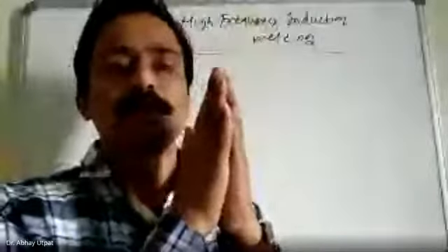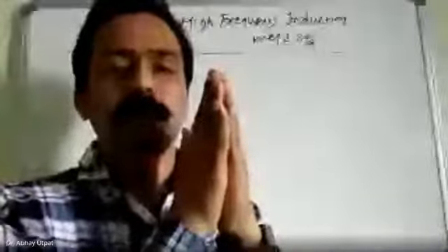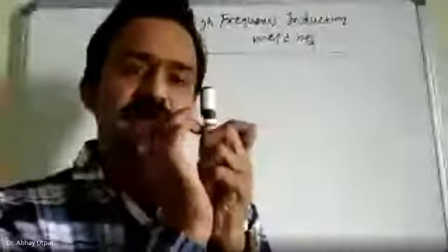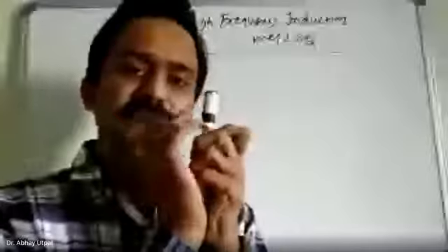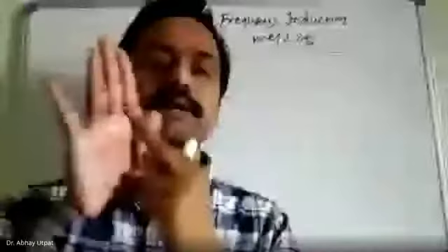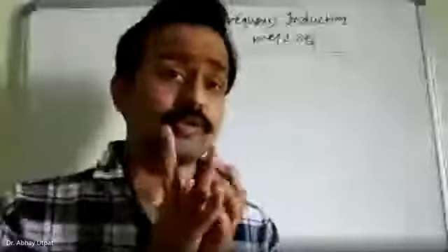The coil is around it. What will happen? Secondary current will be generated inside this metallic part and it will get heated. Once it gets heated, this heat plasticizes the surfaces, and then you can apply pressure for a tight joint.